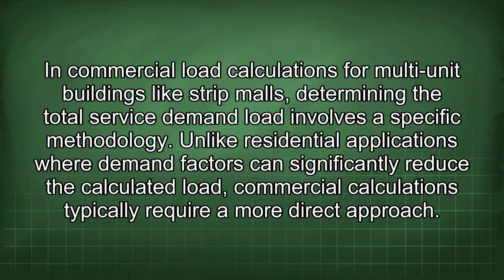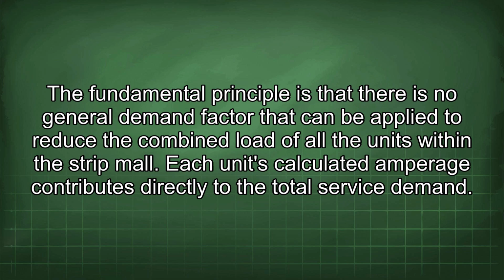In commercial load calculations for multi-unit buildings like strip malls, determining the total service demand load involves a specific methodology. Unlike residential applications where demand factors can significantly reduce the calculated load, commercial calculations typically require a more direct approach. The fundamental principle is that there is no general demand factor that can be applied to reduce the combined load of all the units within the strip mall.